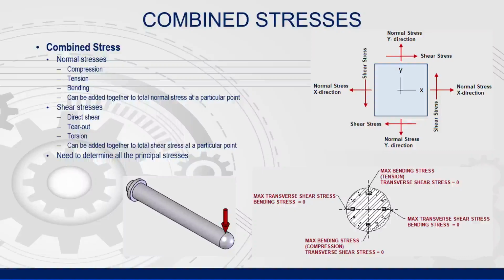When analyzing a loaded beam system, we must first determine the applied stresses. The four possible stresses, again, are axial stress on the ends of the beam, bending stress, transverse shear stress, and torsional shear stress. Once these stresses are known, the next step is to apply them to your stress elements taken at each point of interest.